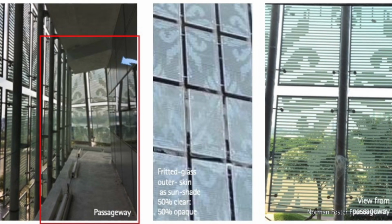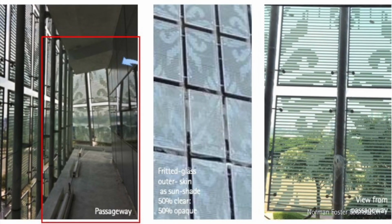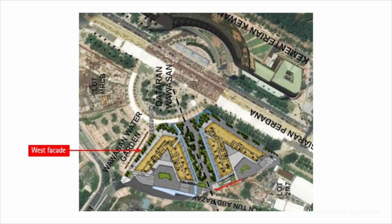And the third image shows the fritted pattern seen from the outside. It is about 50% clear and 50% opaque. And the last image on the right-hand side shows the view of the pattern from the corridor looking outwards. This is the west side of the building, which is the hot side of the building. We angled it so that this protects the facade from the hot western sun.